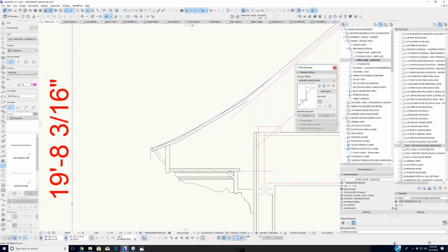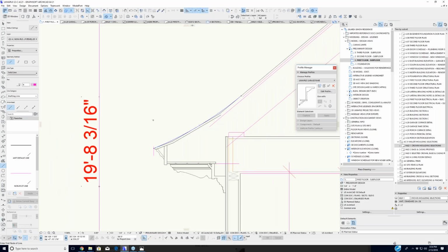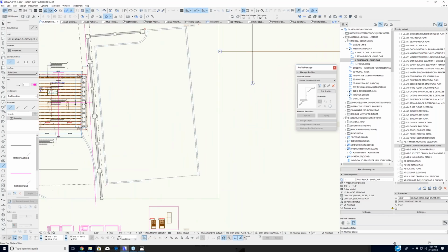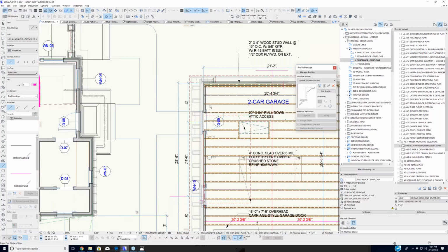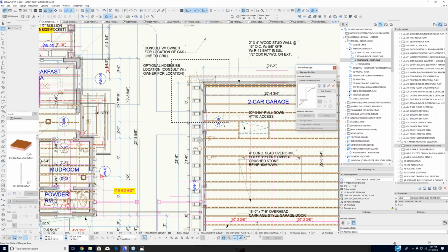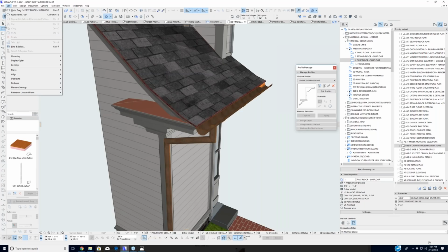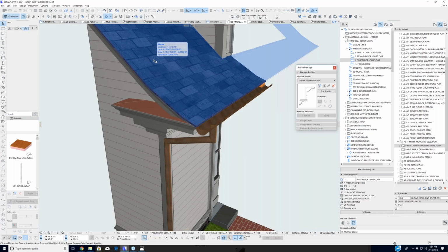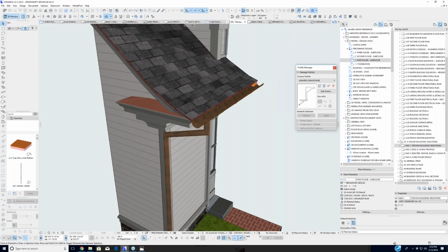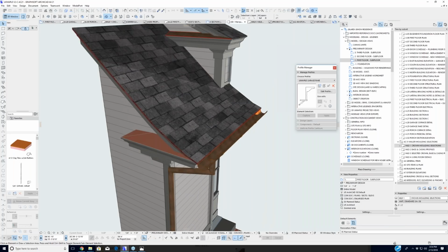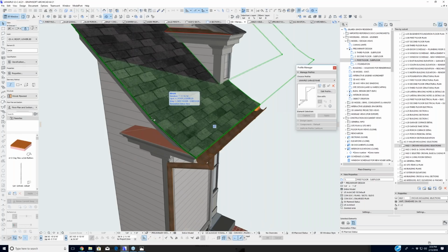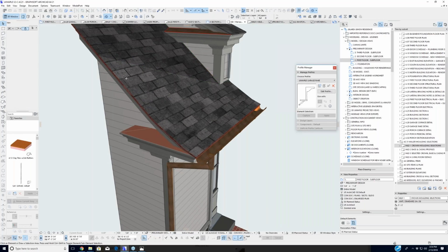So to get this roof to profile like that, jump over here to the plan. It's actually done with a few roof components. Let me just pull that up. Okay, this one I did differently because I had to cut this in. I had to do something here with this dormer. 99% of the time, I turned this into a morph for a different reason. For most of the time, this would have been 3 roofs: a roof 6 inches in at a very low pitch, a second roof, let's say 8 inches in at a certain pitch, and then the rest of this.